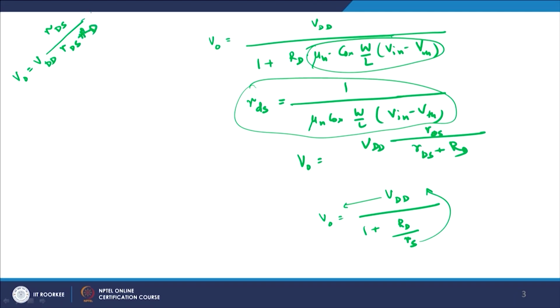RD is the resistance on the drain side, and if you look very carefully, this is how it should look also, because when we were discussing just now, this is VDD, right, and this VDD is broken into two parts as a voltage divider network, and these two parts will be inversely proportional to the resistance offered by this as well as this.